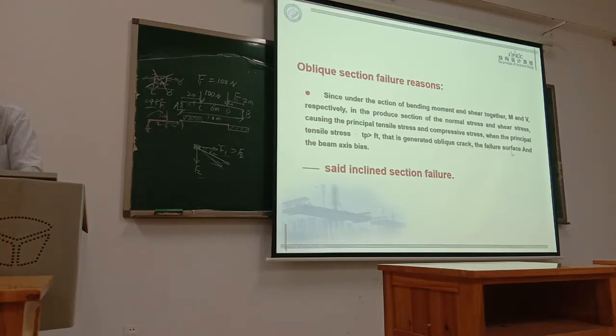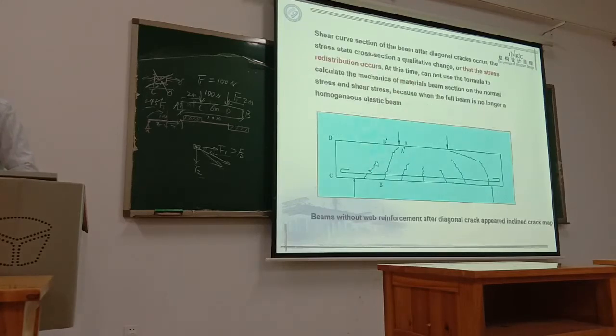The failure surface is oblique, so that's the crack direction, mainly oblique, basically nearly 45 degrees. Because the principal tensile stress is in this direction, the crack should be perpendicular to the force direction.